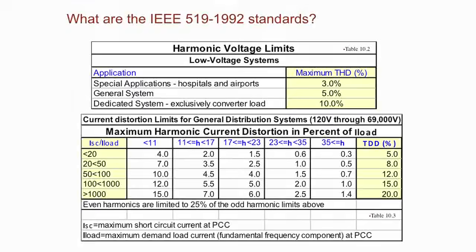If you snuck up on that transformer, walked up with this copper bar and threw it onto that transformer, well, make sure you've got your scope set up and triggered and ready to go, and then run, and measure the short circuit current of that transformer. That would be your ISC. It tells you how much current that transformer can put out. So depending on the size of your transformer, you will fall in different levels of acceptable TDD levels.